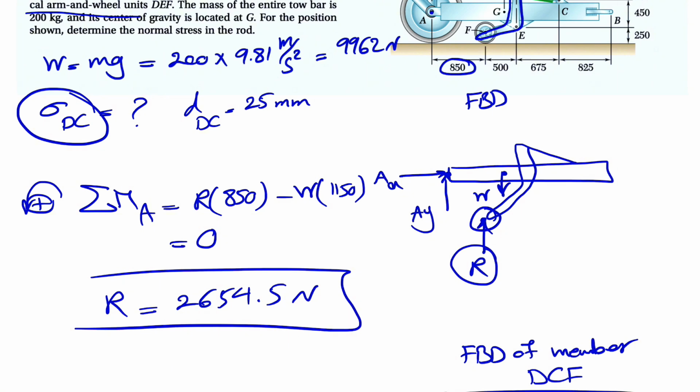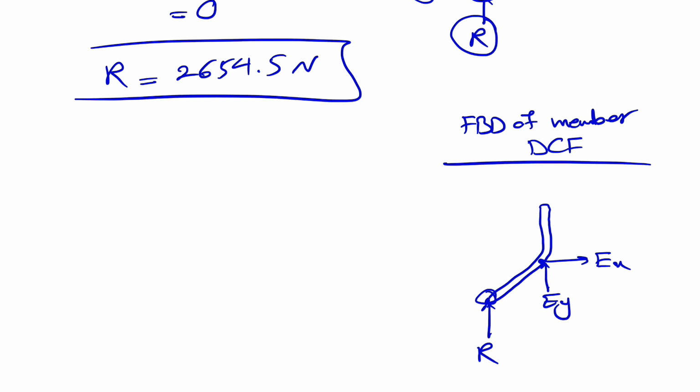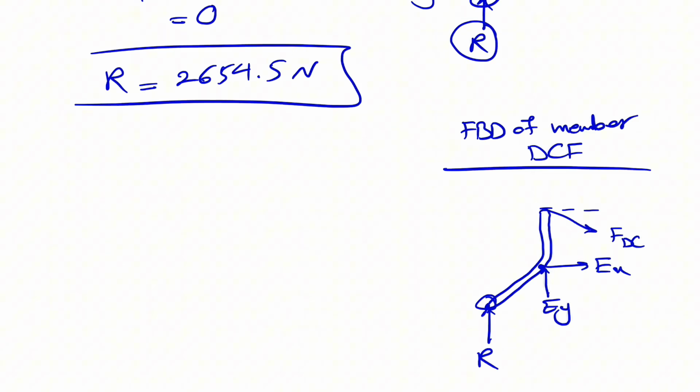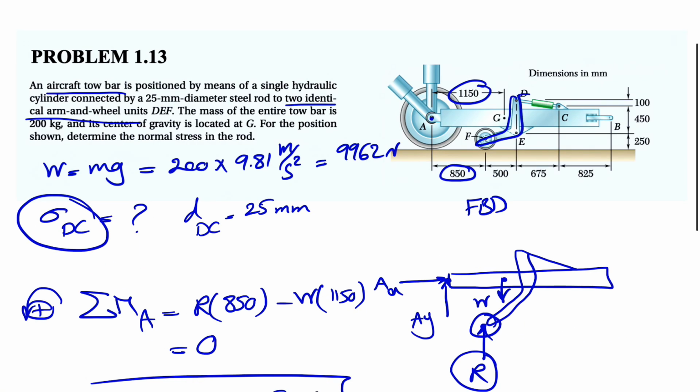So as long as we have the force, we can find the final answers. So let's just consider the force in this direction for now, and at the end if we get a negative sign, it's going to show that our assumption wasn't correct here. We can find this angle easily. It's angle theta, which is the angle with the horizontal, and we have all the dimensions.